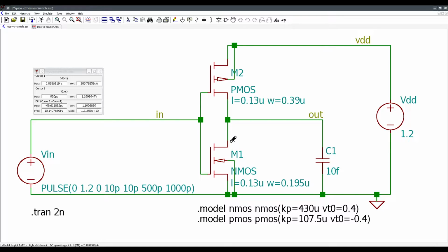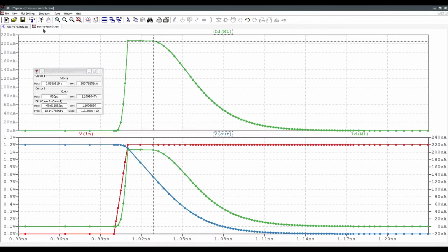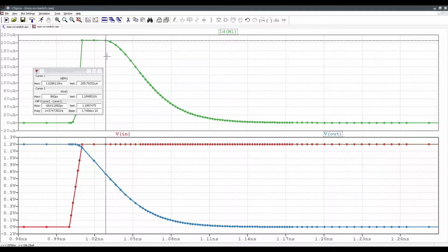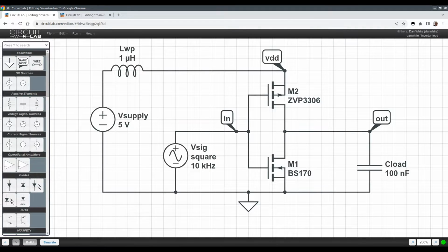We hit the threshold voltage, and from here and below in voltage, the drain side of M1 also has a channel, and we switch into triode mode. Again, we can see this in two different places. One is the constant current, and then the other is just knowing the definition of threshold voltage. Let's switch over to CircuitLab.